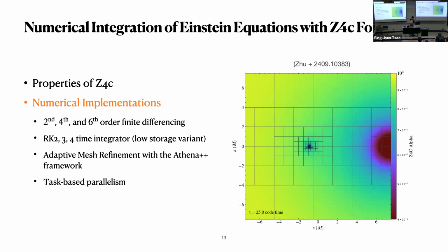So now we have a domain of mesh blocks, which are ordered by some Z ordering, and then broken into chunks and put into each MPI rank. For each MPI rank, we have a list of tasks, including, for example, calculating the right-hand side, doing prolongation and restriction if you have adaptive mesh refinement, and then communicating with neighbors through MPI send and receive.